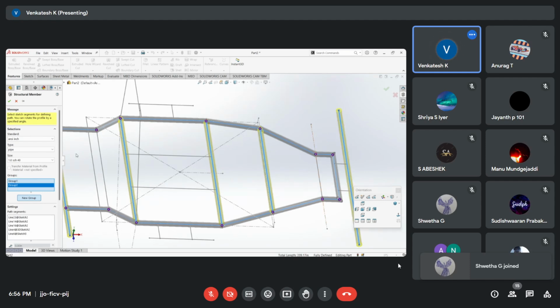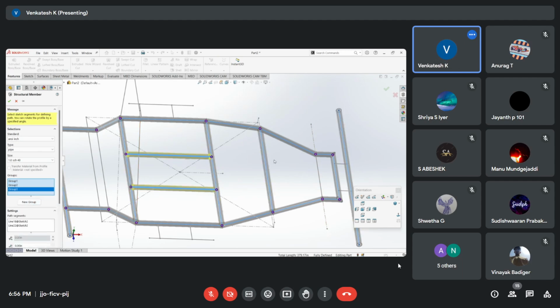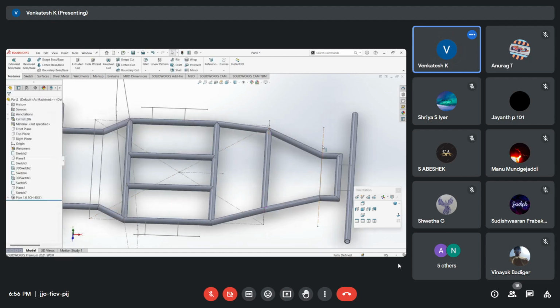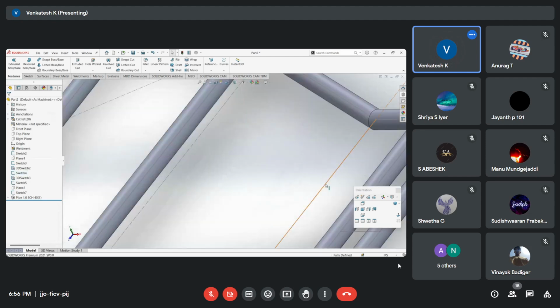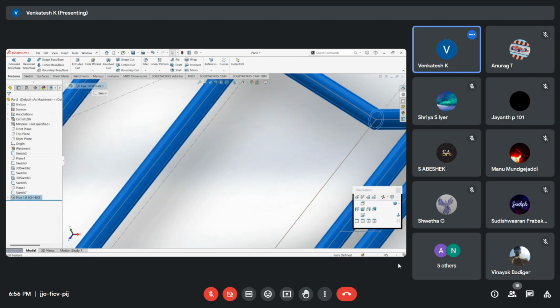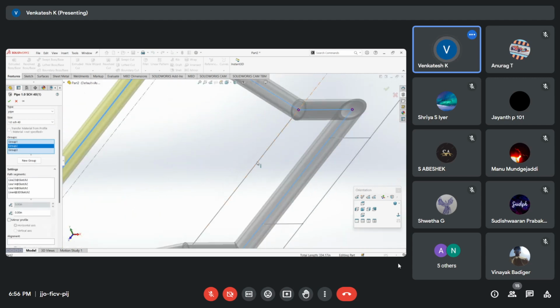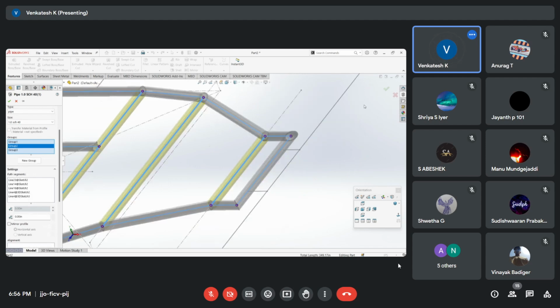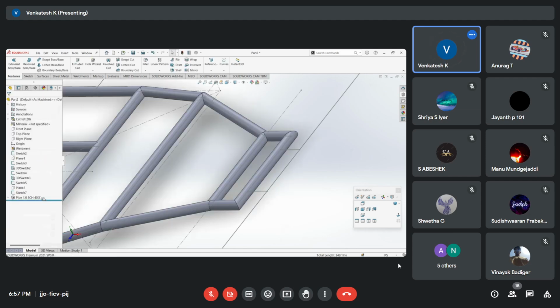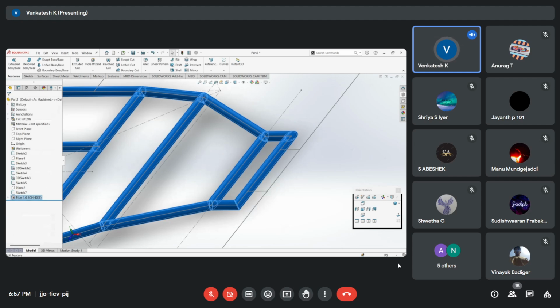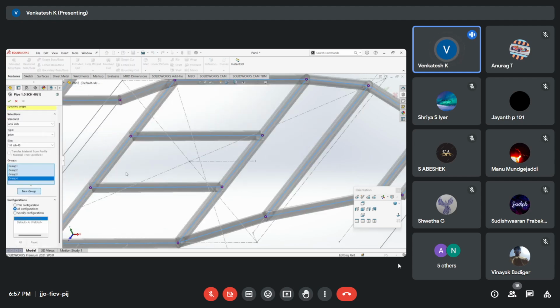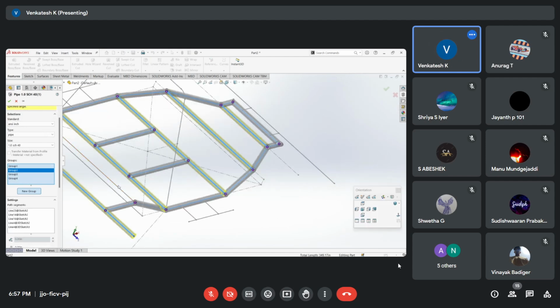Yeah, we'll do it later. Then all the vertical ones again. Yeah, we'll do a small change. Our second group, we won't add this one because that's a bumper, right? So we'll give it a different dimension. Then you can edit the weldment by right clicking on the weldment itself. You can edit the feature, and in the new group, a new group for the firewall now.